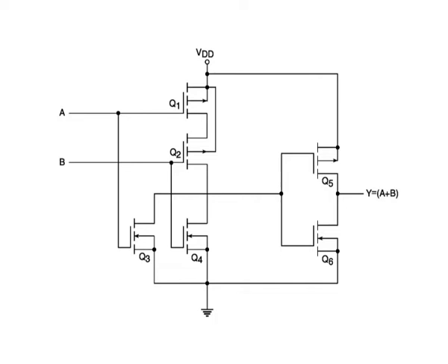The figure here shows the internal schematic of a two input OR in CMOS. A buffered OR gate is fabricated by using a NAND gate schematic with inverters at both of its inputs and its output feeding two series connected inverters.